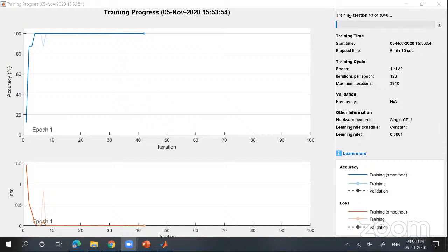Those algorithms have to be converted into fixed point. That is the initial process. Then we avoid using inbuilt functions that are not supported by MATLAB for code generation, and I write the equivalent code for them. Then I can generate code and deploy it. With just one click of a button, as we generated functions today in the app, you can directly deploy that on FPGA, GPU, or your clusters.